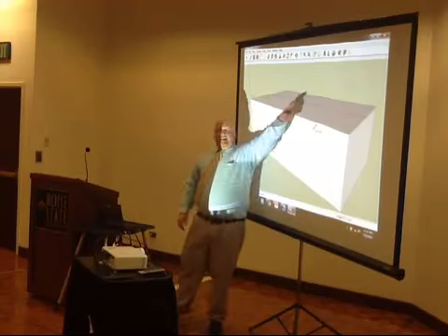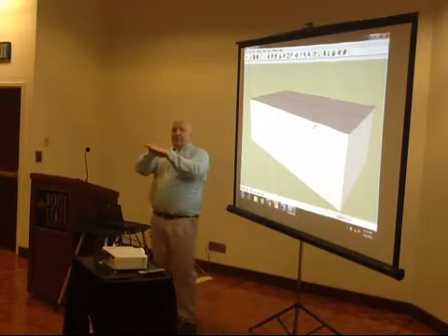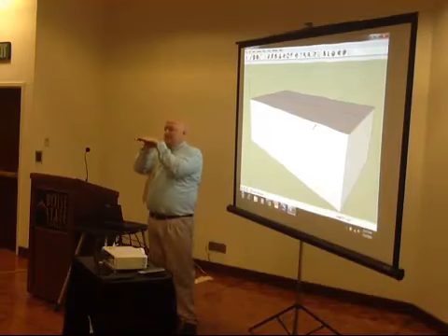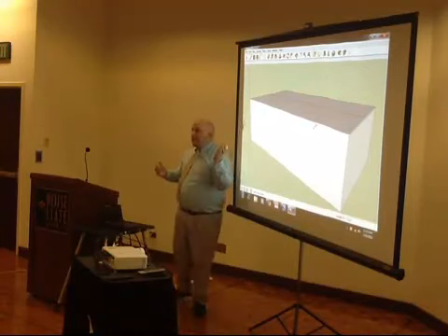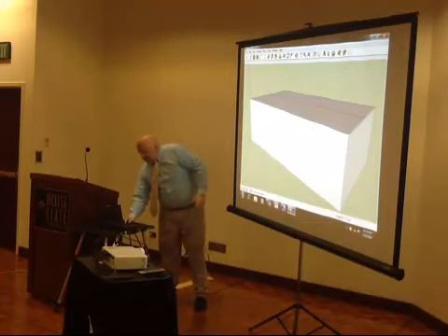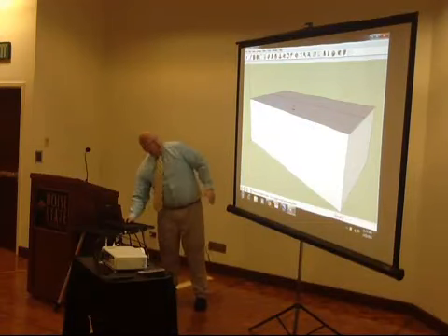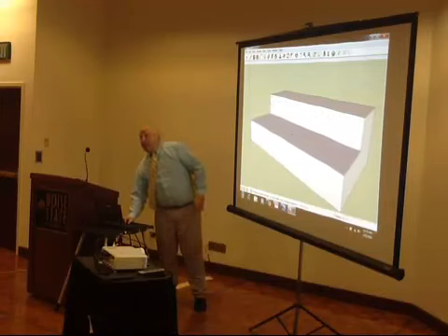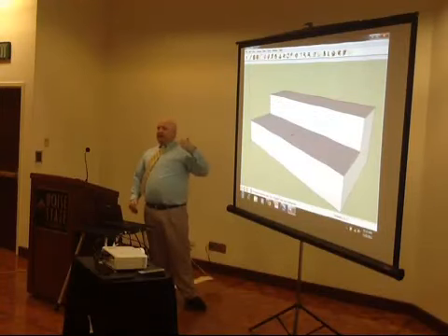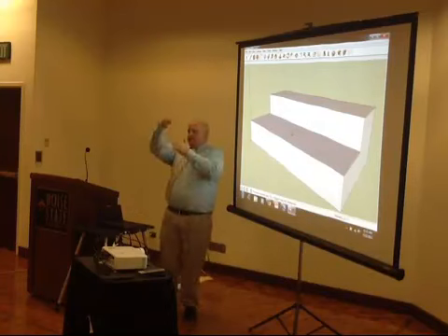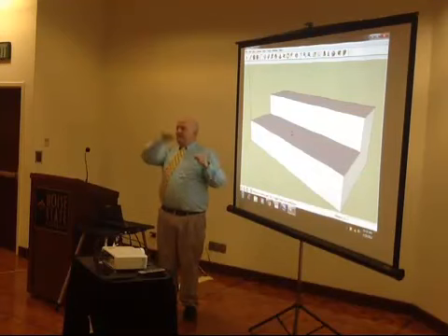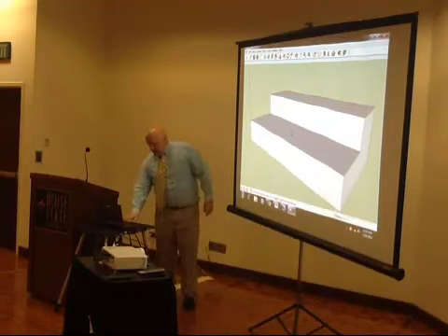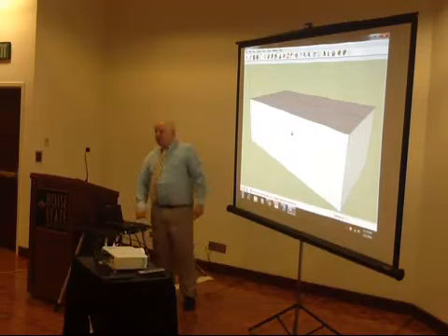What I've done is intersected these two, and in SketchUp, that makes them into two separate shapes, two separate faces. Now I can do different things to each shape if I wanted to. So, for example, if I take my push-pull tool and I go over on one side of this, I can now drag down, and that line becomes a division point. So I can interact with just one part of my drawing based upon the division from that line. But that's not what I want to do, so I'm going to Control Z.